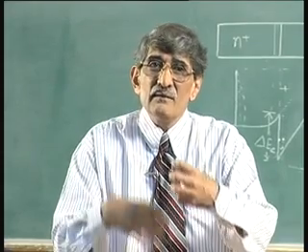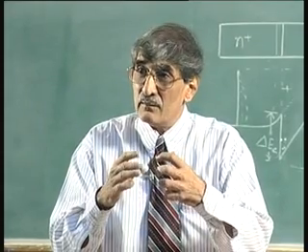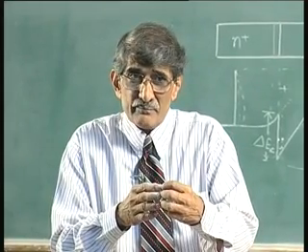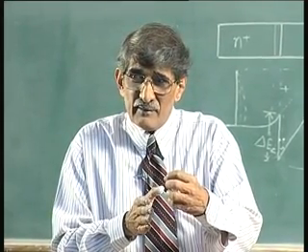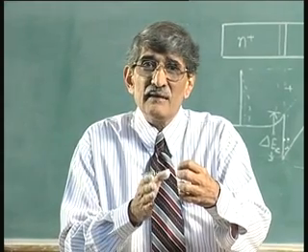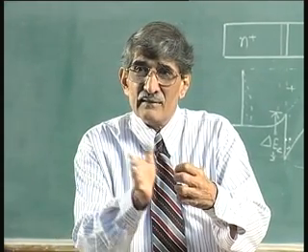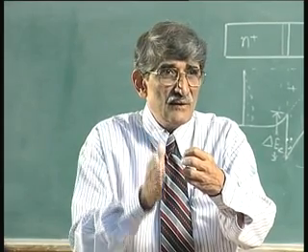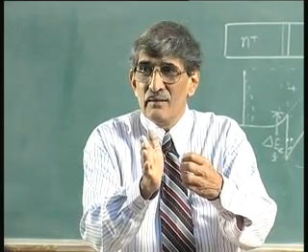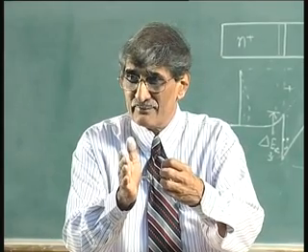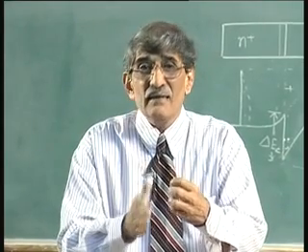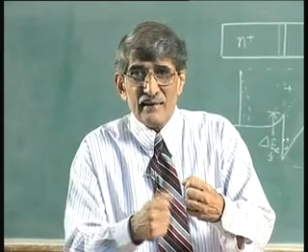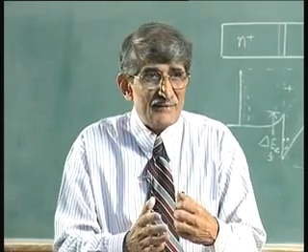That is why the scattering effect at higher temperature is not so much seen, because these are charged impurities. If there is a plus charge, the electron moving in that direction will get reflected. So, instead of moving in that direction, the drifting electron will be diverted like this. That means a change in direction, a change in velocity component, that is the scattering effect that is taking place. It is not like hitting and gaining energy back.